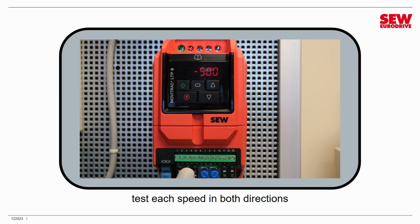We'll check the reverse direction again. That looks good. Go back clockwise. And now we'll check our final speed by turning digital input 3 on. That gives us 1,000 RPM. And we've confirmed as well that we can go in both directions. So we've tested all our speeds in both directions.